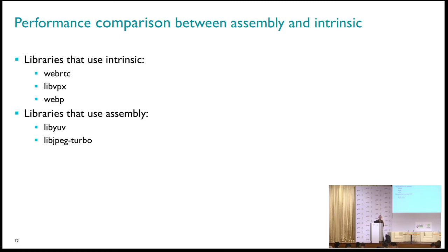Yes, and the compiler has information for scheduling the instructions generated from the intrinsics, so that it will try to make sure that the core doesn't stall and there are no pipeline bubbles when compiling from the intrinsics code. It cannot do that for assembly code. Yes. Actually, I'm working on a Ne10 project, and in my experience, intrinsics are pretty good.